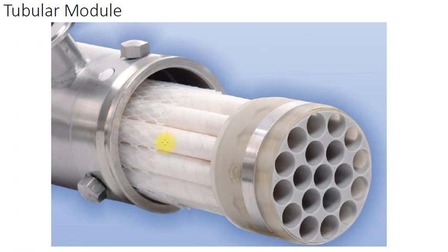So this is the same concept, only the difference is you have the tube as a membrane. So these are the ceramic tubes. Generally the inorganic membranes are used in the tubular module only, because in this geometry you have the higher strength of the material, if the membranes are inorganic.